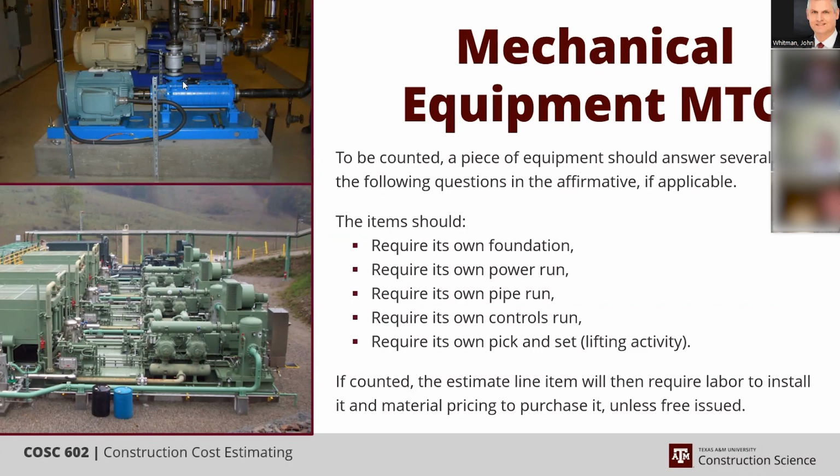you can't see it, but there's probably at least one instrument on this that is checking for vibration, and then just away from it, there's going to be instrumentation checking pressure and flow, monitoring what's going in and coming out of that pump. And in addition to pressure, it'll be a differential pressure in addition to that. So if you can answer in the affirmative a number of these, you count it.